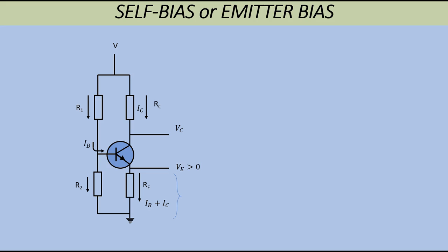Now we're going to see the importance of this resistor is to act in such a way as to produce feedback to the circuit, and it's a negative form of feedback, and that has the effect of keeping the transistor more stabilized and less susceptible to variations in the collector current. Now the collector current can increase for the reason I've mentioned already, that we might replace this transistor with another one having a different value of beta, but it might also increase for other reasons.